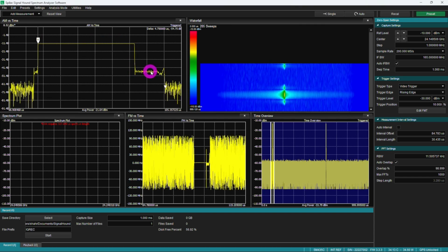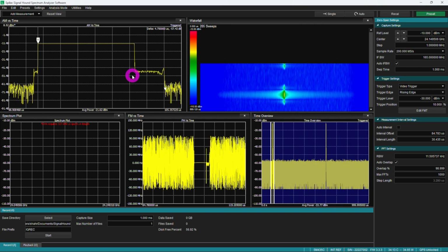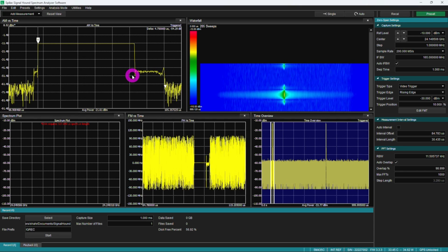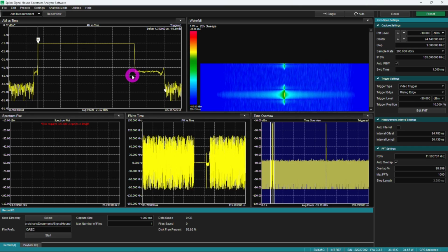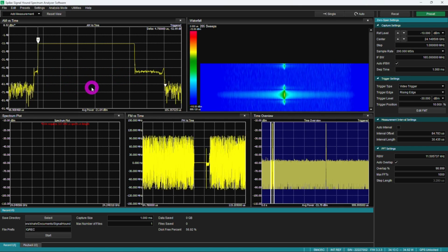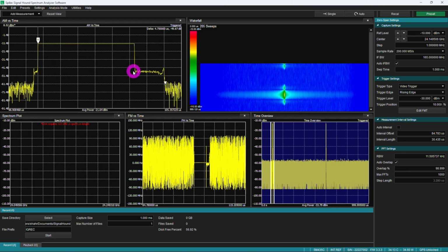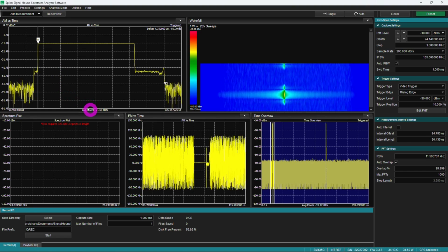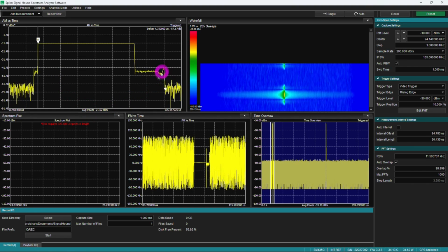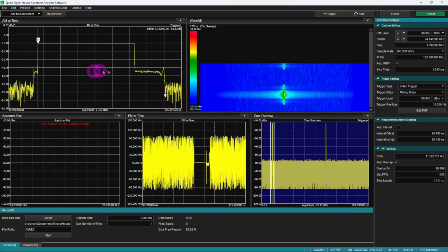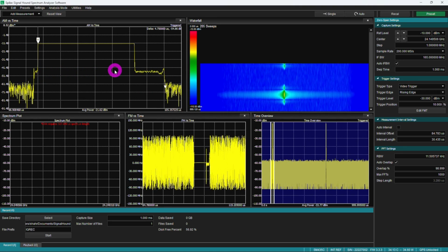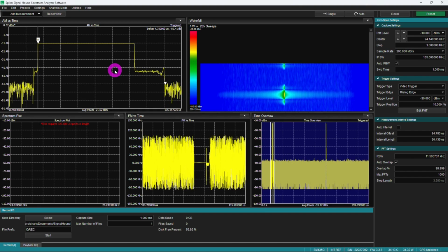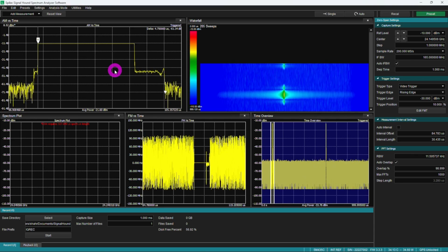Then it drops, and there's a little bit, and it drops again. Now, during this time is most likely just leakage from the chip itself, because even if you turn the power amplifier off, I think it's only 1 or 2 stages, you still get some leakage out, and that leakage isn't necessarily very well controlled. That's exactly what happens during this. So by looking at this pulse so quickly with the software, you can measure exactly the individual characteristics of how those pulses behave. And you can also see that there are a little bit of spikes in the amplitude variations as things come and go, because when you turn these on, of course, there are brief moments where you have some dynamic behavior from the PAs powering on. They're not exactly fully correctly biased yet, and you get some of this interesting behavior.